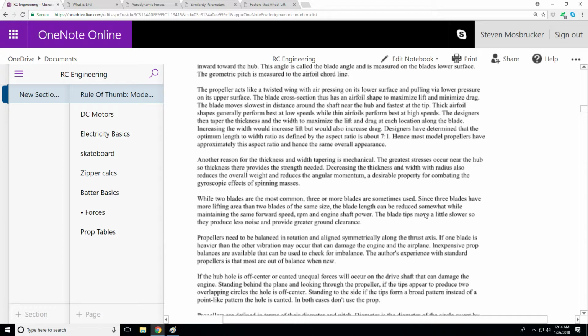So acceleration is a change of velocity. If you want to change the velocity very quickly, but you only have a certain amount of torque, and torque is a force, right? So that's your acceleration. If you only have a certain amount of torque and you want to change speed faster, you're going to want a lower mass.